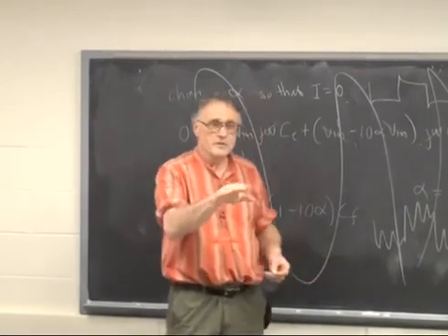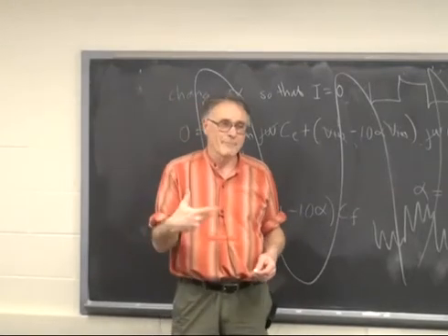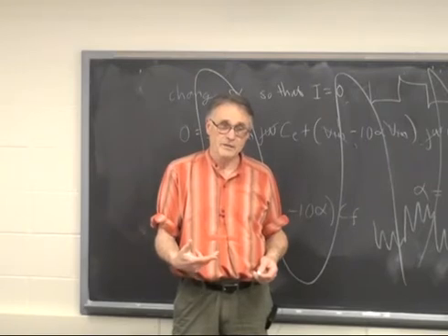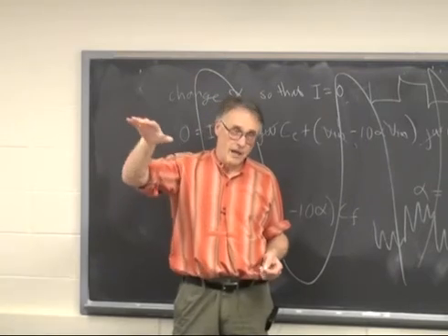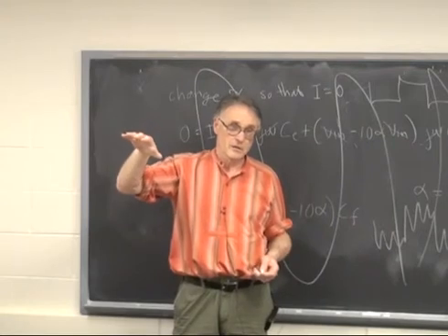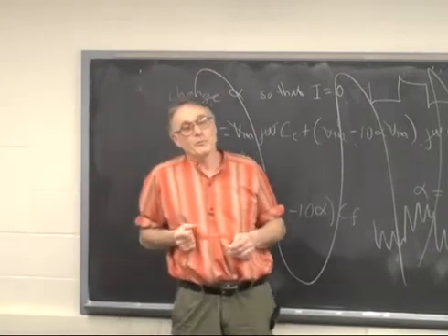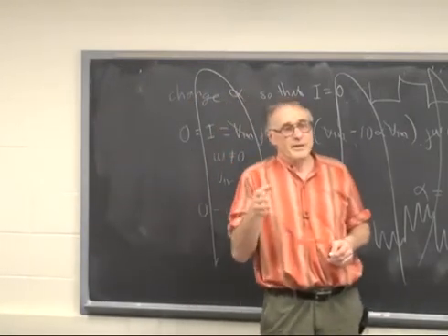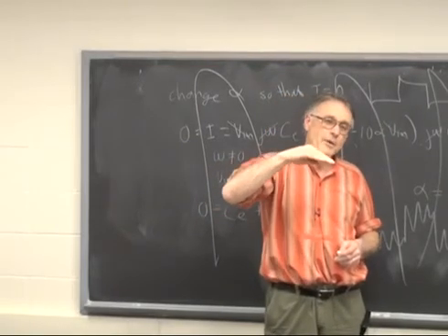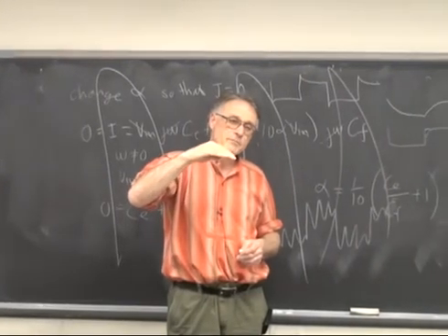So if you were going to do this automatically, you'd have to know a lot about the noise, and I'll bet you could classify it, because the system becomes very high in high frequency noise as you jack up the gain at high frequencies. It becomes noise dominant. So if you were to measure the spectrum of the noise coming out of this system, you could watch the tail come up, and just before it starts to flatten out at high frequencies, you stop it.